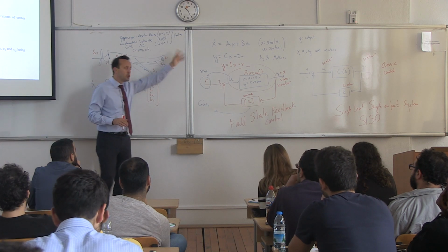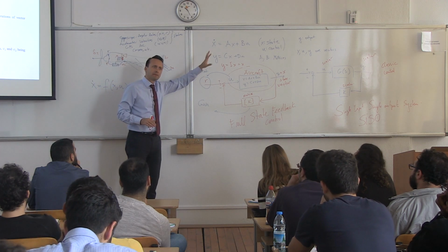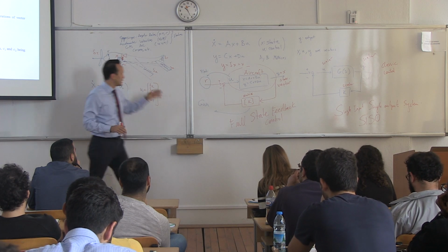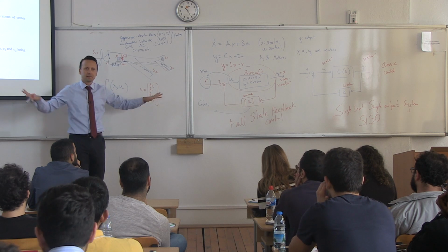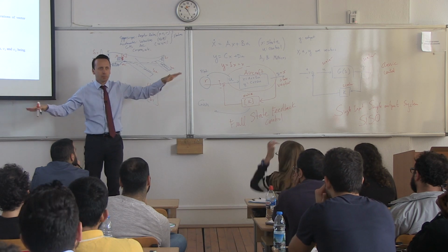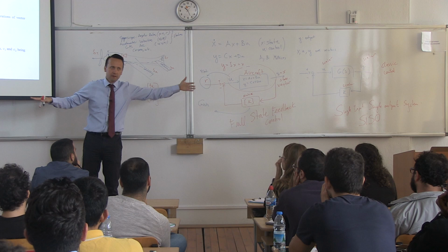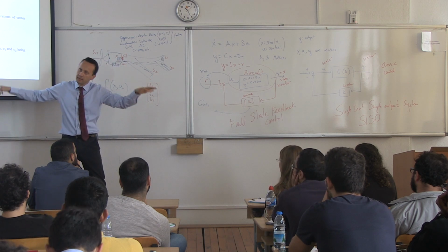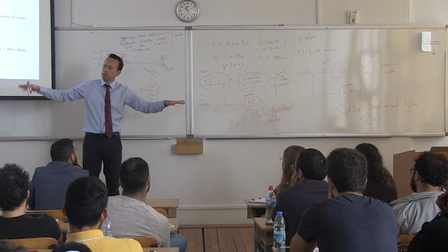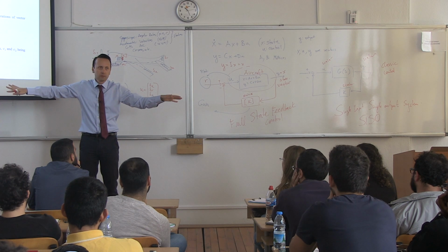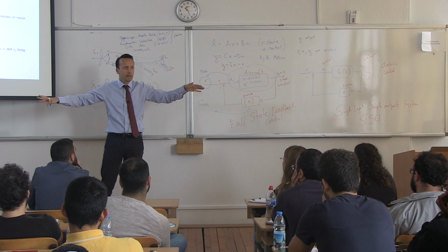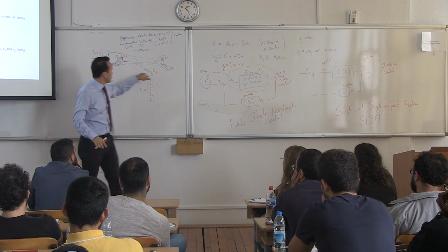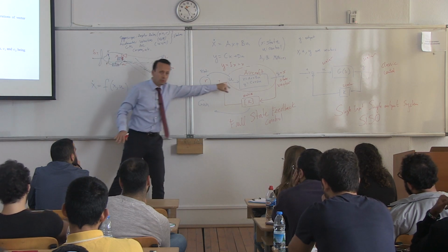I will call things U, X, Y, whatever, it's a lot of symbols, but reality is really here. You have control surfaces that move around so that the airplane does something. If you have a gust coming from one side, the airplane needs to do that, right? How does it do it? Well, it changes the direction of the ailerons, right? Gives a little bit of an aileron input and moves to the other side. So it would be here. So that would be the control input U.